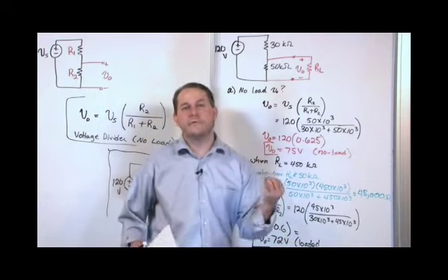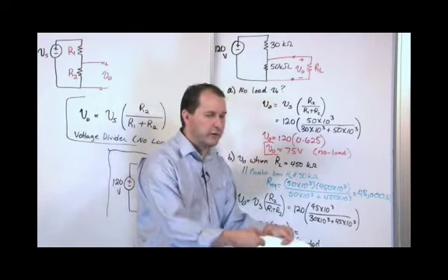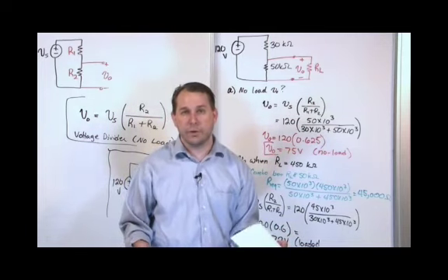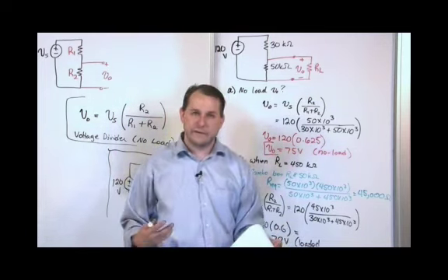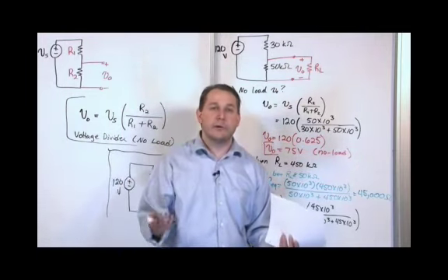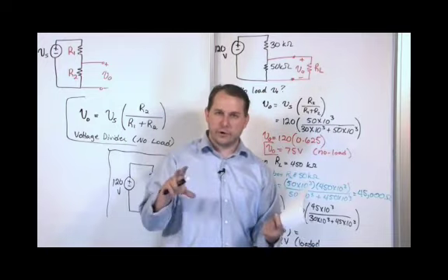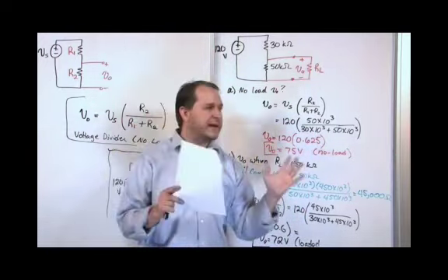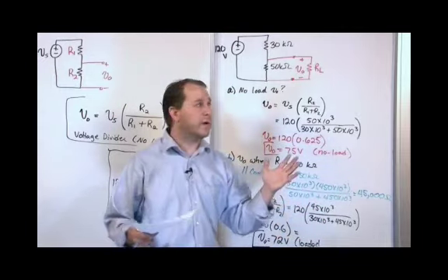So most voltmeters, when you hook them up to a circuit and measure, the internal resistance of those meters is very typically in the millions of ohms. Very, very high resistances, so as not to alter the circuit, because ultimately you don't want any current flowing in that voltmeter. You just want a pure voltage there. So there are other considerations, depending on what you're trying to do in your circuit, and what the purpose of what you're trying to do is.